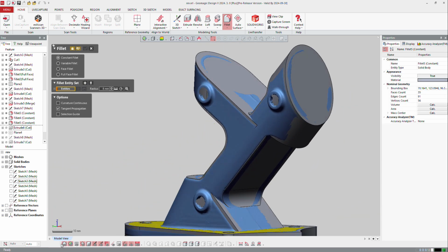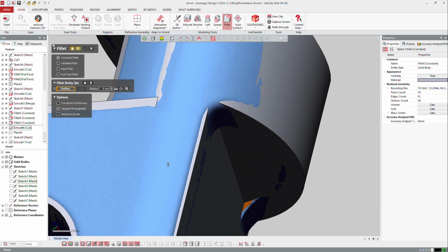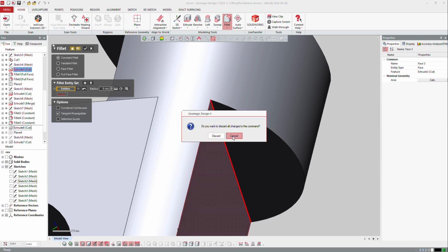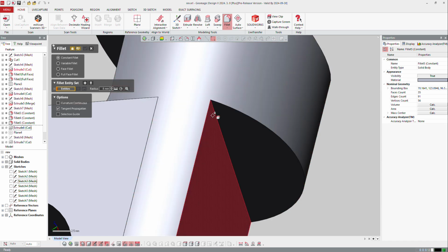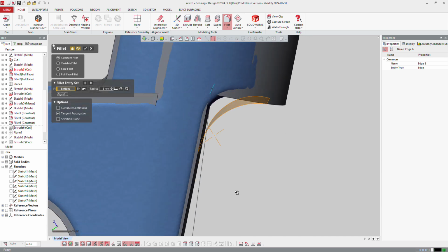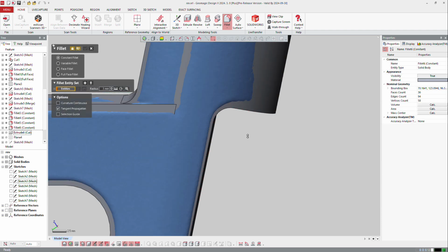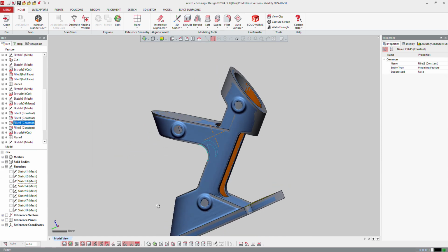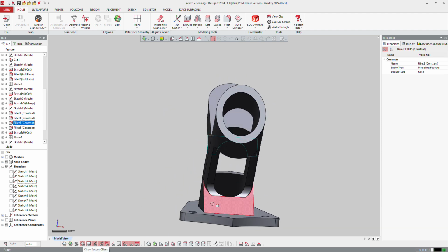And now I got all my main fillet done. If I hide that, I can see I forgot that one. Right mouse click, well, it's there already, I'm already in the function. So I can just select the edge here, display again the mesh, and this should be 2 or 3. And okay. All right, so now I can go back to the end. So right mouse click, roll to end, and the software reproduce everything here on the part.